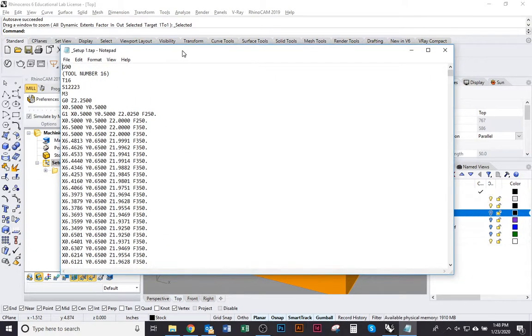All right, and then what happens is automatically a Notepad file should open. This is actually the .tap file. And this is what's called G-code, and you can see it's a series of X, Y, and Z values. In other words, these are like locations. So the router is interpreting this code, and it's moving according to the movements that we've written out in a sequence in this file.